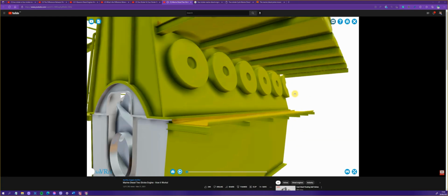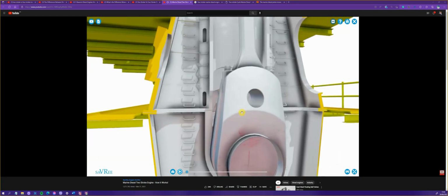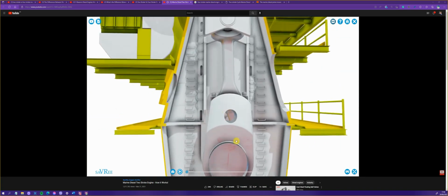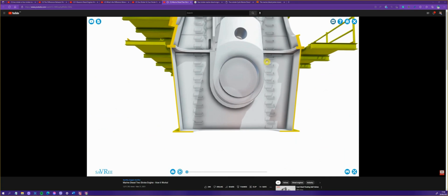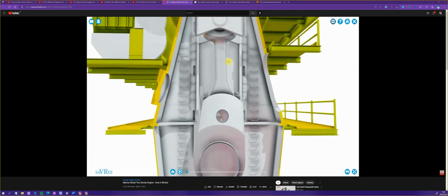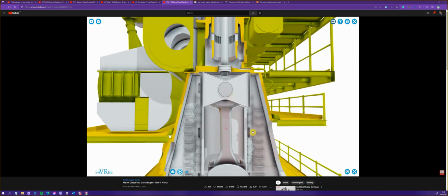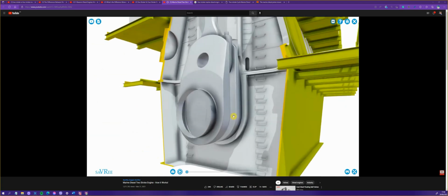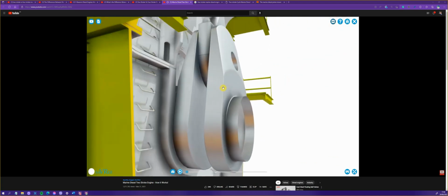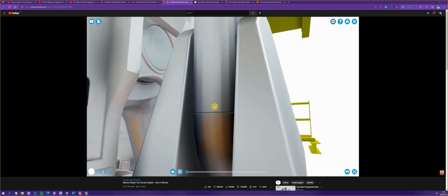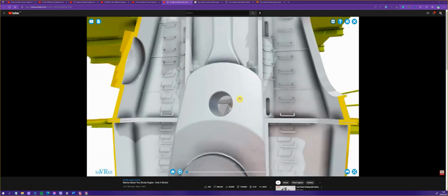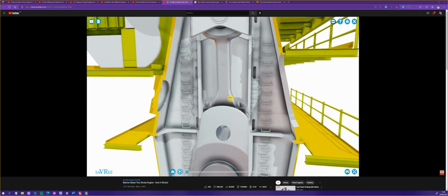Why do we have them? Well, inside this engine, there's going to be lubrication oil. A lot of it. Tons of it. Usually sitting at the bottom of the engine here, but also covering all of the internal surfaces of the engine, especially within the crankcase. If this oil gets heated up, maybe there's a hot spot between the bearings. Let's just say for a moment where our conrod connects to the crankshaft. There'll be a bearing that we can't see, about here and here. And if this bearing gets hot, it heats up the lubrication oil, and you end up with lubrication oil vapor.